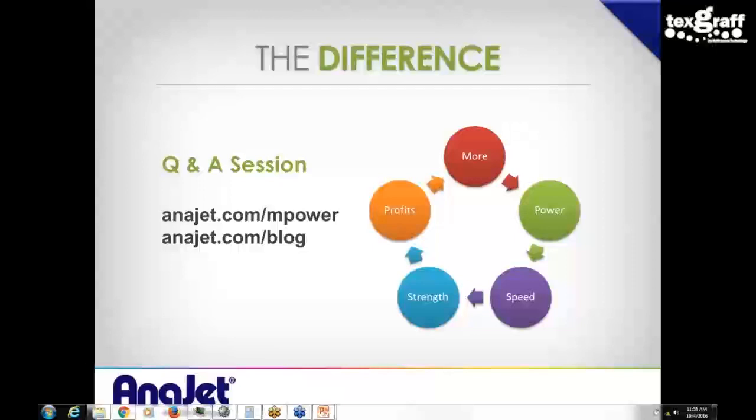Where you end up having ink loss is if, say, you haven't used the printer in 4 days, and you want to get ready to start printing. That's fine. First thing you do is a nozzle check. The nozzle check tells you which nozzles are firing and which ones aren't. If you let the printer sit for 4 days, it's probably not going to be a perfect nozzle check. So you do a light head clean. That light head clean will push the ink back down out of the print head and clean off the tip of the print head with the wiper blade. Then you do another nozzle check and you're back to printing. At that point, the nozzle check is back to being perfect.